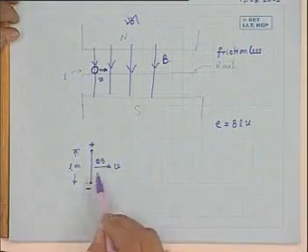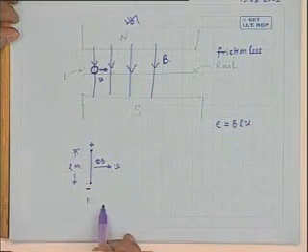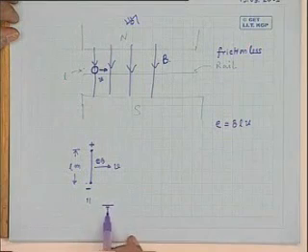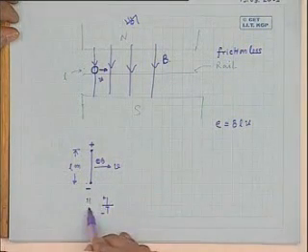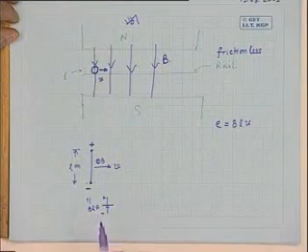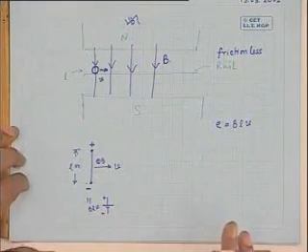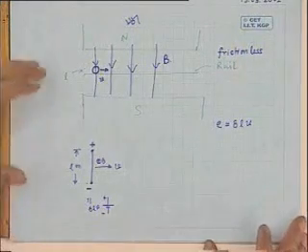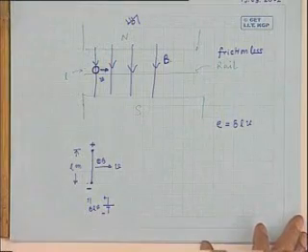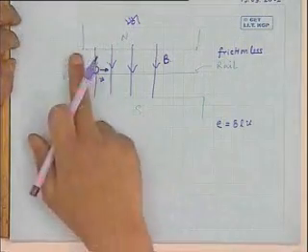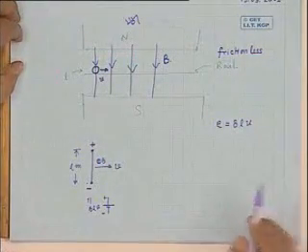Therefore, at any point of time this conductor is equivalent to a battery with this side plus and this side minus, and the magnitude of this battery is BLV. Therefore, this is a very simple generator. Of course, to develop such a generator is very impractical, because you would have to put north pole, south pole like that all along the track.